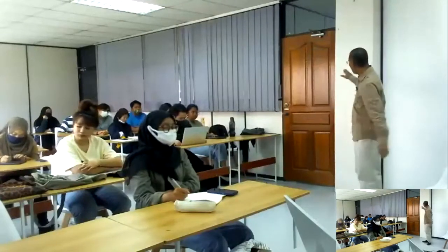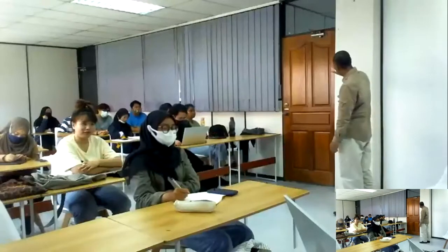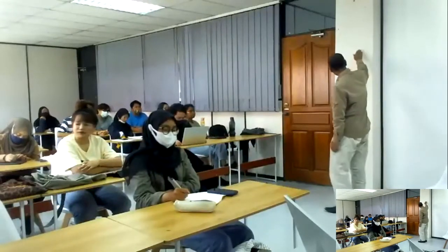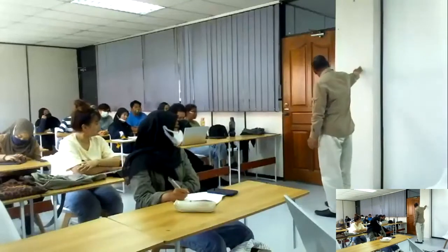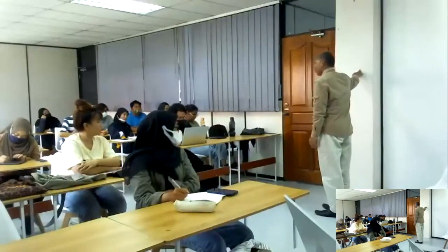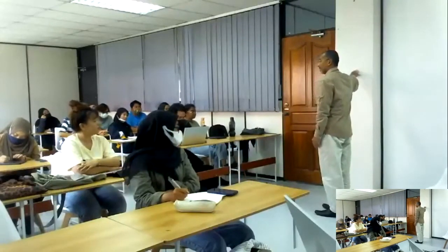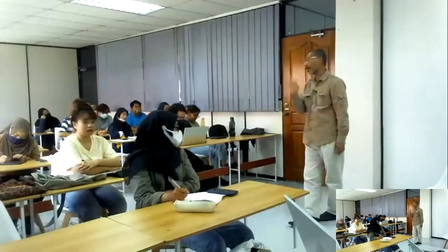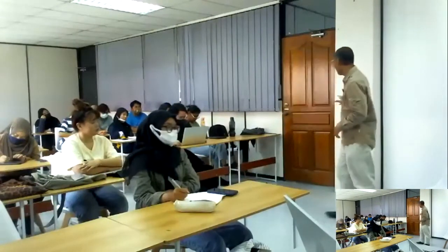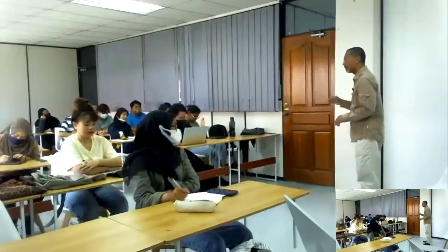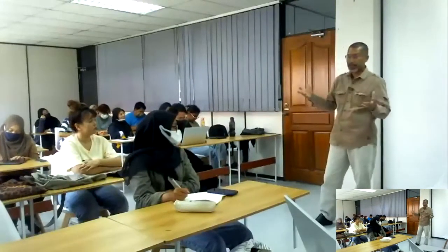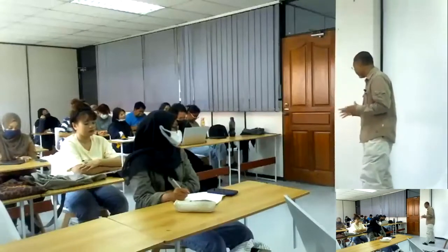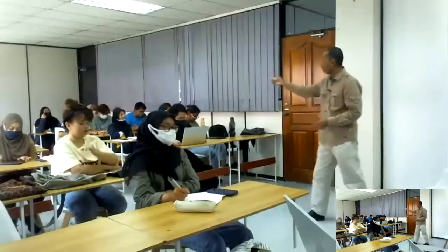So if, based on data, the slope is safe this way, then we make it even longer to ensure it's actually safe by a factor of safety of 2, because we don't know everything about the soil. We know only about the thing that we test, for example, that we take to the lab. And like I mentioned, the soil from one point to another point could be different.